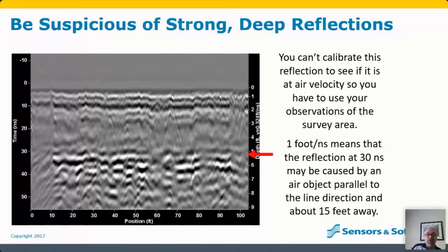And I've watched people get data like this and say, oh yeah, we obviously see the water table right here, right? Flat reflector, looks good, water table, everything matches, great interpretation to put in my report to the client. And totally wrong, because it was an airwave and they didn't do their due diligence.